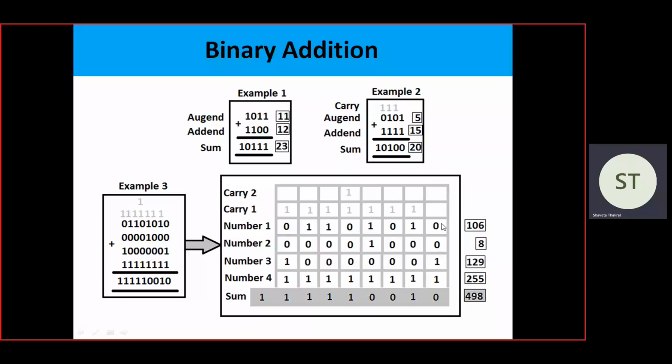What we do, when we start adding these 4-bit numbers, we see how many ones are there in the addition. Like here if we are adding 0 0 1 1, 2 ones are there, and 2 ones represent an even value. So if we are adding multi-bit numbers and the number of ones is even, in that case remember that the sum will be 0 and the carry generated will depend upon the pairs of ones.